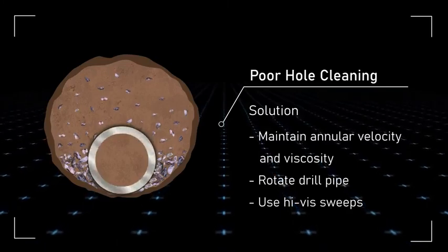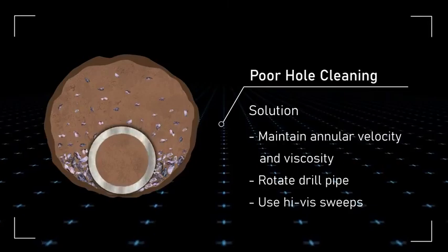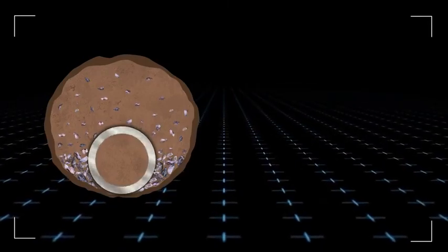High annular fluid velocities assist cuttings removal. The pumping rate, fluid properties, and rotation speeds also affect hole cleaning.